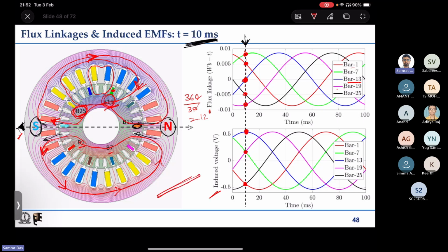Now these rotor bars, what are they? They are simply conductive bars, with some induced EMF across the two ends of each bar. If we have to represent the equivalent circuit of this bar electrically, what will it be? There is some return path for everything, because all the bars are shorted from both sides. If we just have to represent this bar, then what is that?